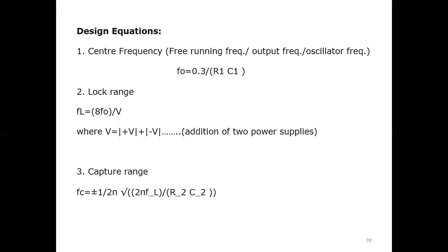This is the design equation for the different parameters. First one is the center frequency, f0 equal to 0.3 divided by R1C1.